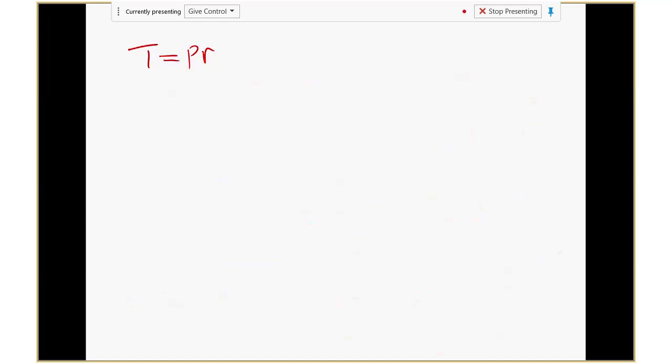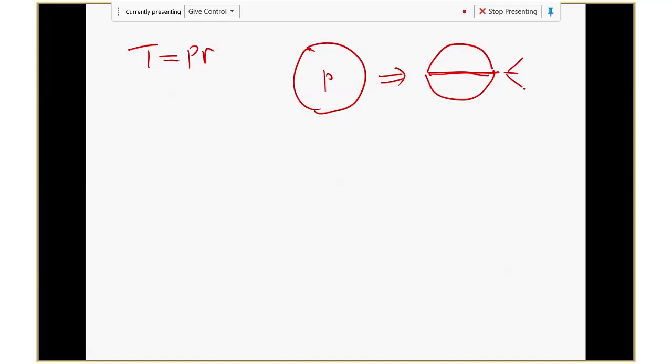Imagine you have this cylinder, right? So I have this cylinder here under pressure P. Now, what if I can make this equivalent to this one here? Let's say, imagine I put a membrane here. Now if I have a membrane there, I can divide this into 2 parts. One part will be this half, one part will be this half. They will be the same, right? So therefore, let me say if I have a pressure vessel like this, basically a half circle.